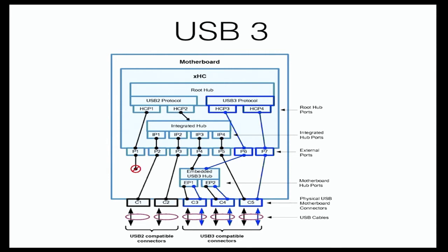The super speed can go to an XHCI controller, and the high speed one could go to an EHCI controller. That's legal. And you have to keep track of them. The software has to keep track of all this. And you better pray you're not too colorblind.